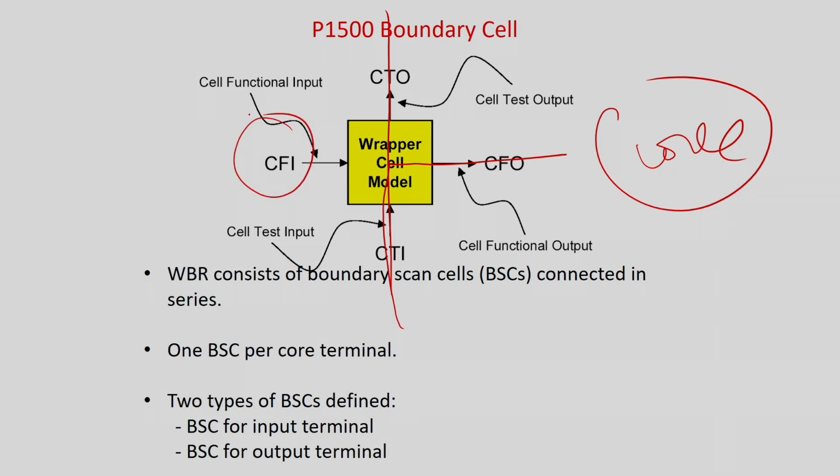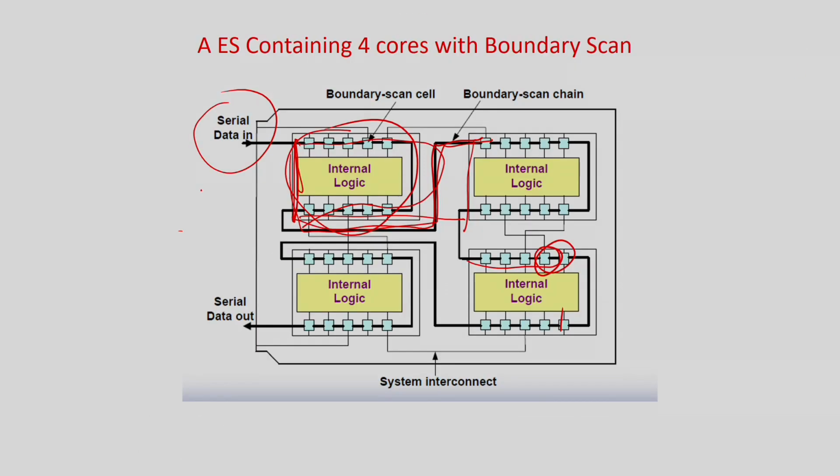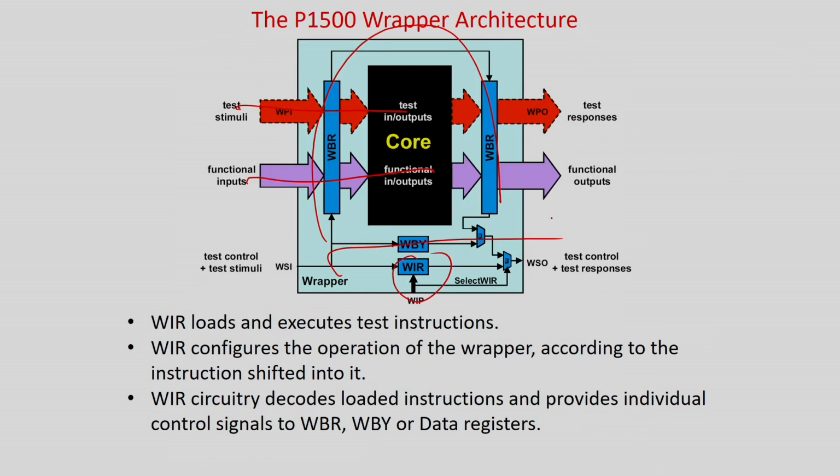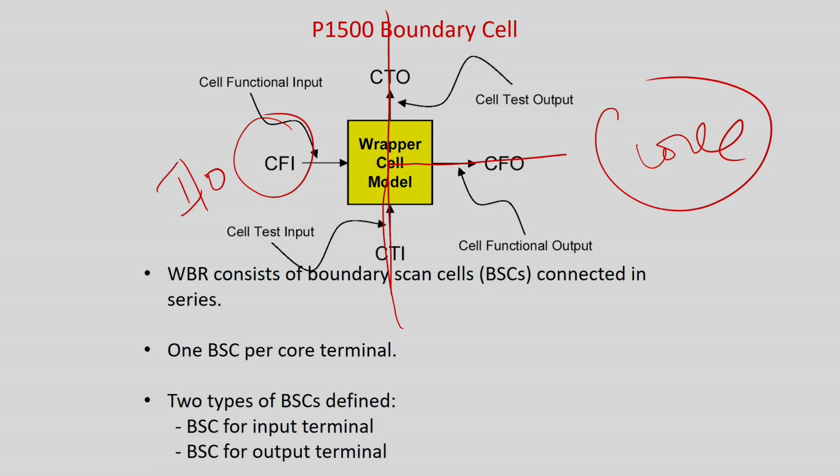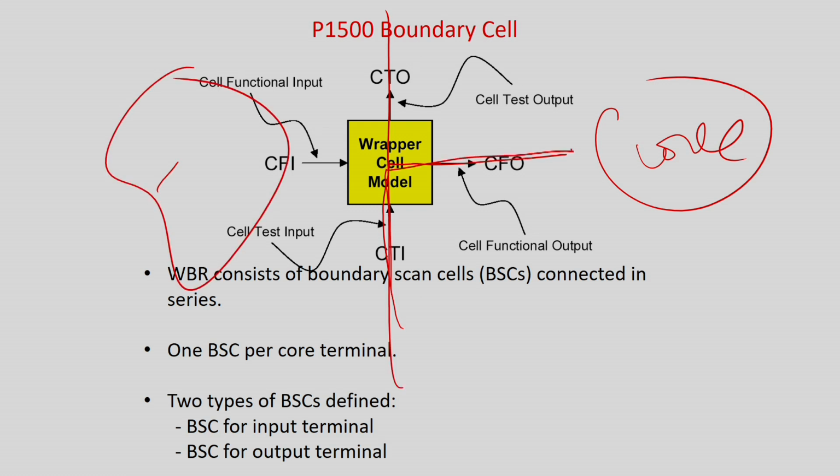If you want to give the test pattern, basically if it's an IO pin directly, like this pin, like this point, if you want to access something, you need not scan in the value here, you can directly give it as the output. But if you want to give some test value at this pin, you have to scan in over here. So accordingly, you can easily appreciate that I can actually change this model. So if this is the input output pin, you can directly give the test pattern here, or you can also give directly the normal input output pattern over here. But if it is not an input output pin, maybe it is covered by some other core, then you have to scan in the value and apply this. So a simple standard multiplexing arrangement, as you can easily appreciate.